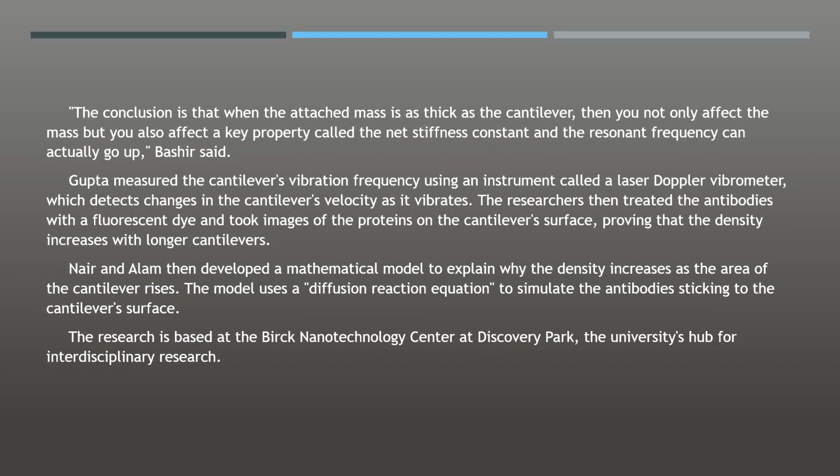The conclusion is that when the attached mass is as thick as the cantilever, then you not only affect the mass, but you also affect a property called the net stiffness constant, K, and the resonant frequency can actually go up, Bashir said. Gupta measures the cantilevers' vibration frequency using an instrument called a laser Doppler vibrometer, which detects changes in the cantilever's velocity as it vibrates.